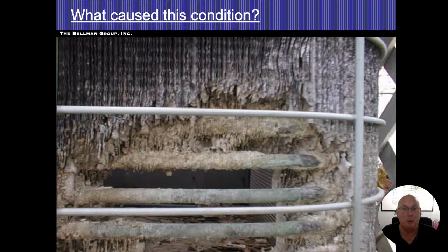Now, it didn't hit the copper tubing. It didn't damage that, but the fins that are on there, it did damage. The tubing itself is where the refrigerant runs, and then those up and down fins, you can see how tightly spaced they are together. So we get a lot of airspace touching the metal when it runs through. We do have to keep those clean.